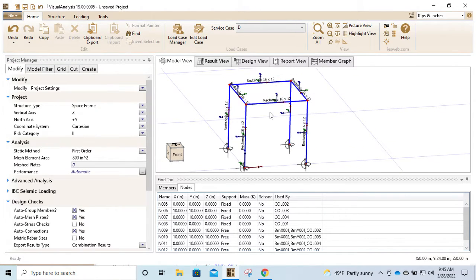Okay, so what this model says is that at those beam to column intersections, all of those members are rigidly connected, right? If that node rotates, all of the members connected to that node rotate the same amount, in any direction. If it translates, all of those elements translate together. And at the base, we just have it all fixed, okay?